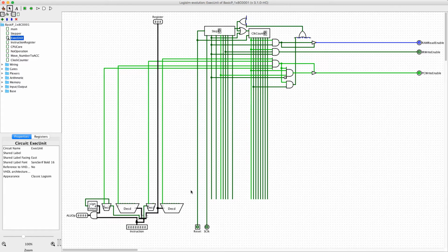Well, part of it anyways. I haven't completed it yet, but this is what I decided to do to my original CPU design after I saw the relevant videos by Ben Eater explaining signals and signal control. So, like in the last video, we have different fields. The instruction class basically has just 1 bit to it, and if the class is a 0, then it's not used by the arithmetic logic unit. If it's a 1, then it is used by the arithmetic logic unit.